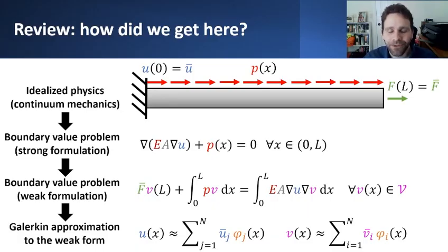In fact, we're going to restrict attention and represent both our candidate solutions for the displacement field and for this virtual displacement field in terms of a finite set of functions, and construct these representations for the trial solution and for the virtual displacement functions as basically just a linear combination of these basis functions taken from some finite dimensional function space.